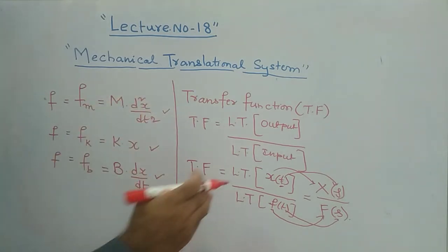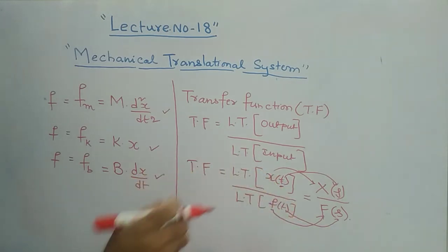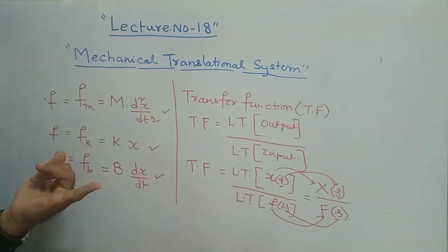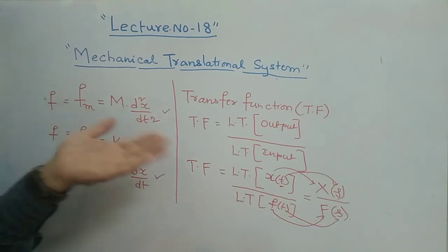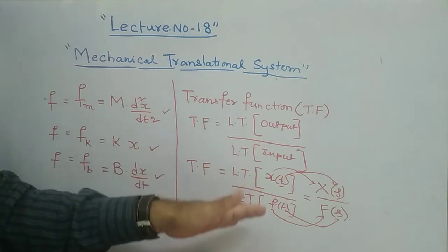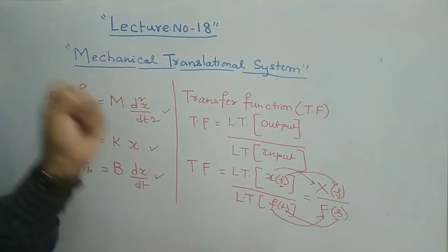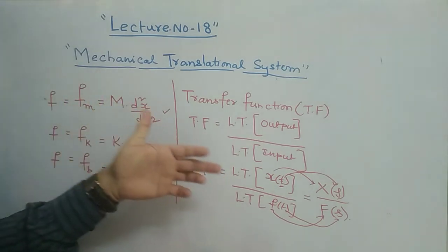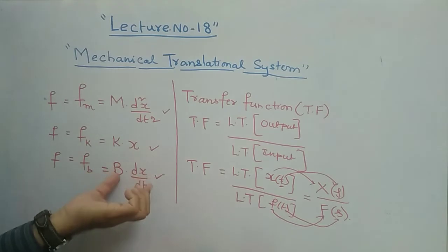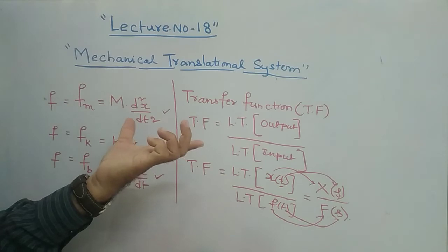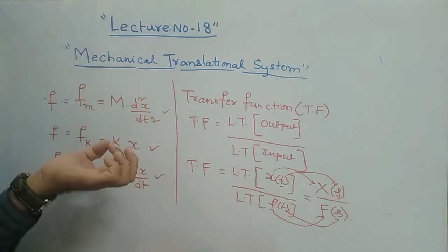Now, to find the transfer function for the given mechanical system, we need to write down the differential equation first. Directly it's not possible to find the transfer function. The first basic step is to write the differential equation, which consists of these forces and elements.